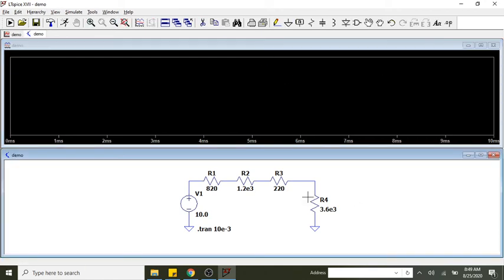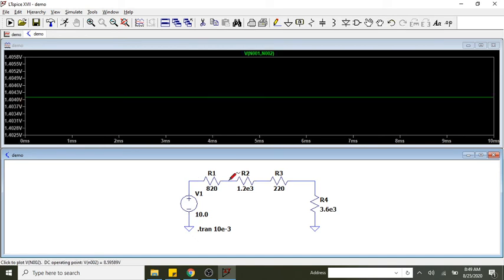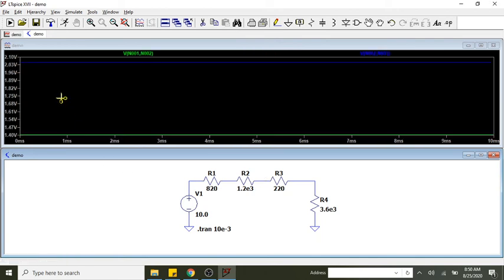What about voltage? To get the voltage, you need to click and drag. So I'm going to left click on the left side of R1, click and drag, and when the lead becomes black, I'm going to release. That's showing me about 1.40 volts for our VR1. Let's see what VR2 is. VR2 is the blue, and that's just over 2 volts.